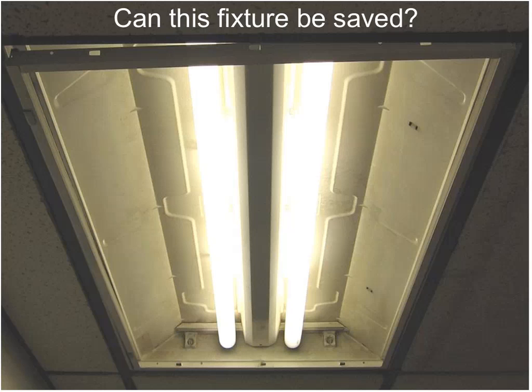Now, since I can't take all of you in the field to see some actual fixtures, this photo is going to have to be the next best thing. So let's put what we've learned so far into action by evaluating upgrade options for this typical recessed troffer. So looking at this, what can we find that gives us clues about the condition of the fixture? Well, for one thing, we see that we have a couple lamps missing, so maybe this area was overlit.